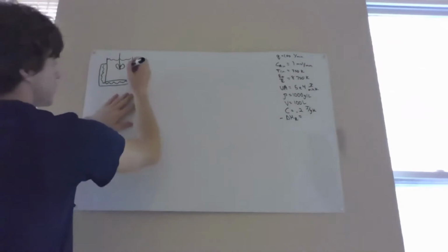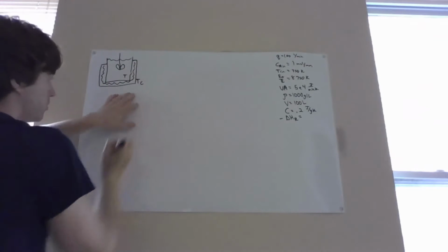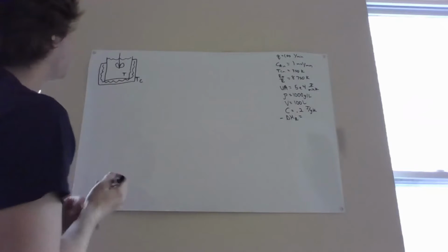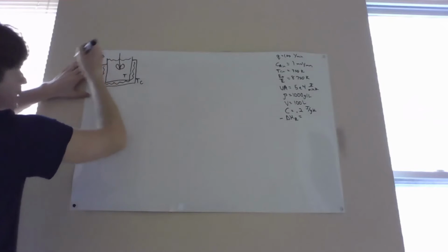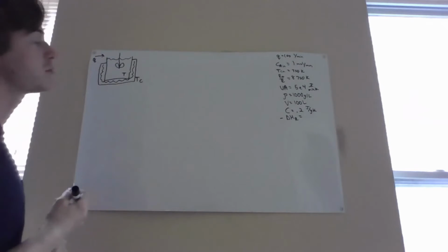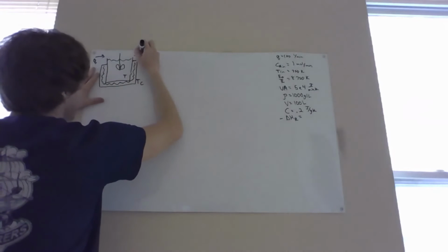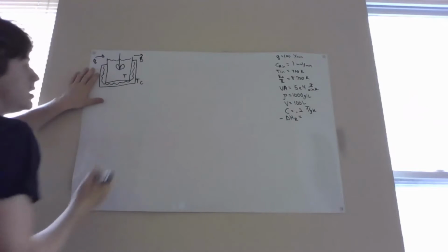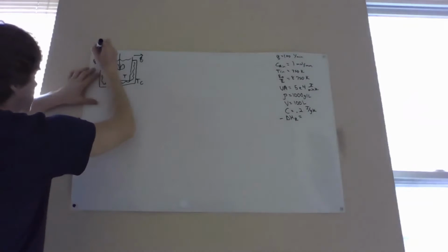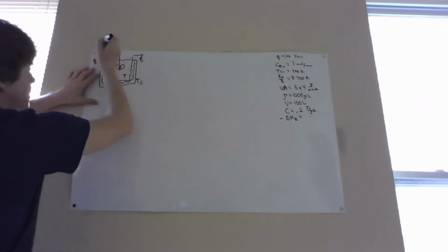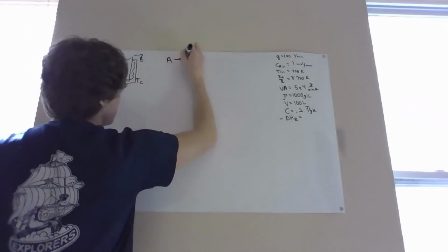So there is a temperature inside the reactor, and there's also the temperature of the coolant. Additionally, we'll have a flow rate into the tank, which is given as Q. It equals 100 liters per minute. Since it's a constant volume reactor, the flow rate in will be equal to the flow rate out. There's also the concentration of A going in for our reaction. So our reaction is a first order reaction from A to B.